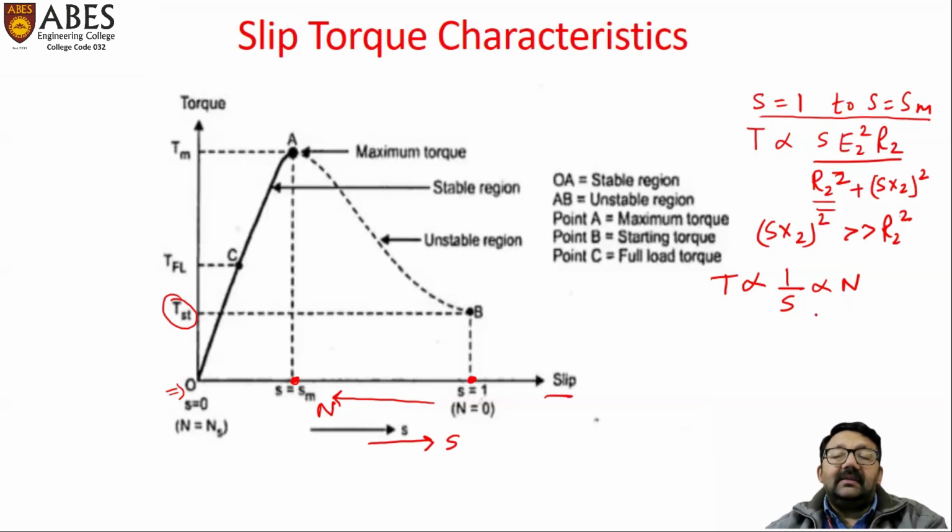This is because in this region, the induction motor cannot operate. Here, what happens is, as the motor speed increases, the corresponding value of slip decreases, and decrease in slip means increase in motor torque. And as the motor torque increases, the RPM of motor further increases. So torque and speed both are directly proportional to each other.